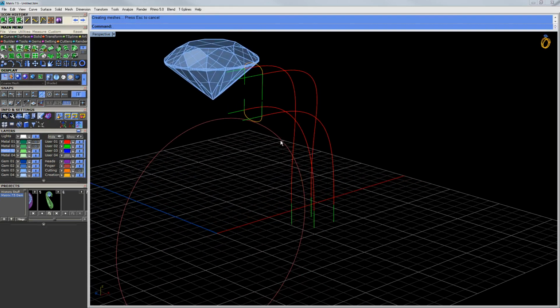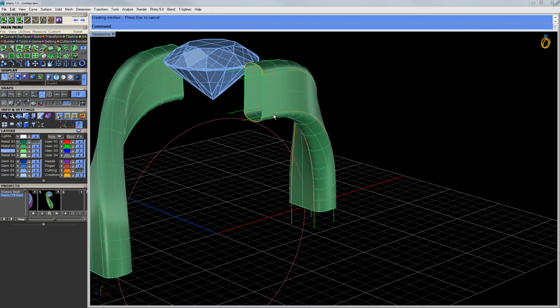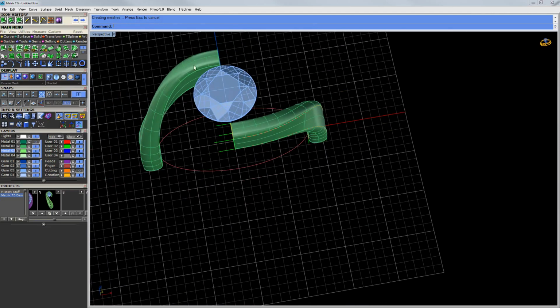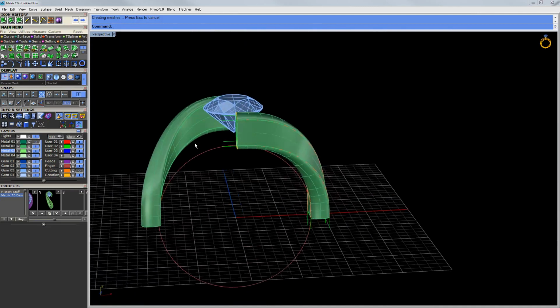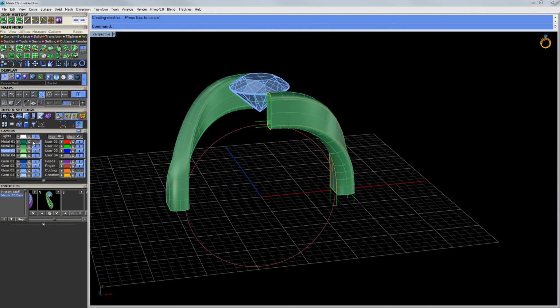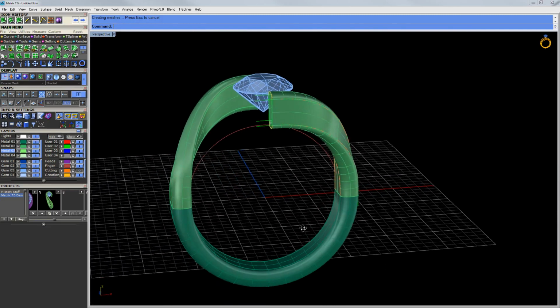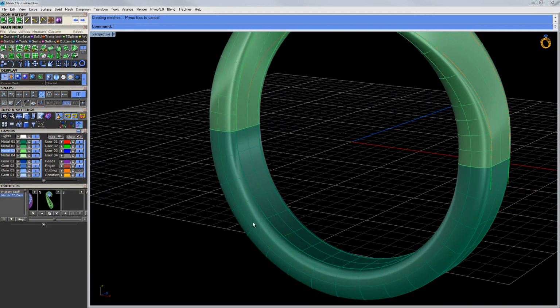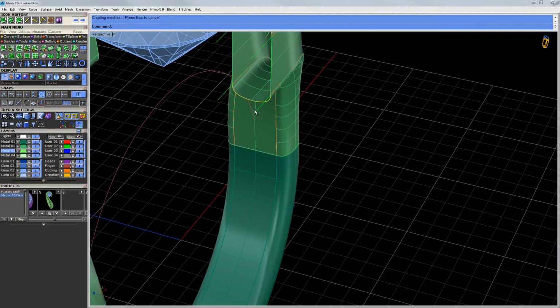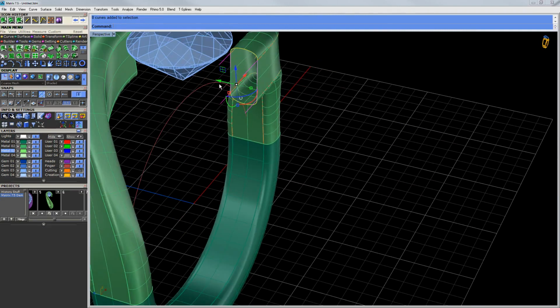So the green tick marks, so to speak, were our starting point. And then we did a series of lofts and sweep 2 to create the top portion. And then for the other side, we did a rotate with copy. And then once we had that, we did a series of sweep 1 and sweep 2 again on the bottom portion to create this. So everything started from our original sets of green tick marks.